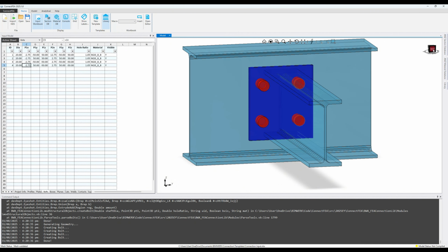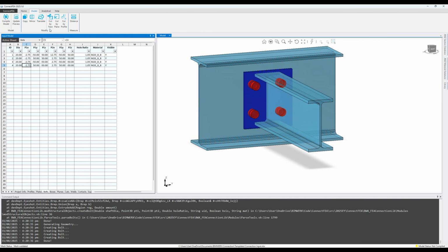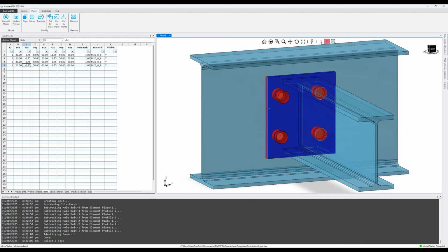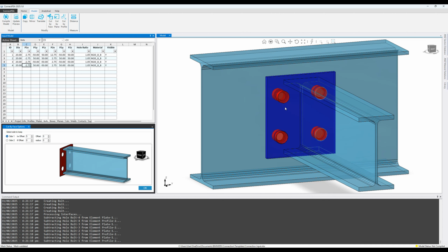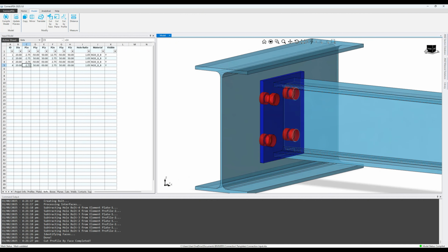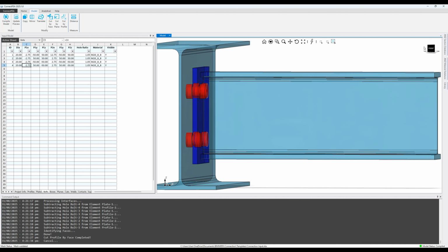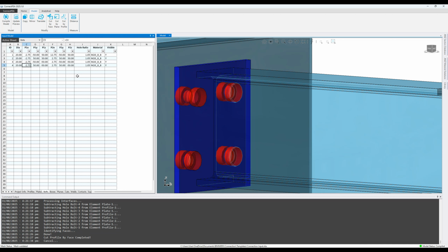Again, I'm setting some values equal to the other ones so that if I make a change like the diameter or the positions along the Y spacing and the Z spacing, it's easy to just quickly update one and that'll update all. Then I'm using the machining tools here to cut or trim that beam element back to the plate so that it connects nicely. And you can see there, ConnectFEA picks up those faces with its subtractions of the bolt elements automatically. And while I did that, I noticed I made a little bit of an error in one of the formulas there for the bolts.